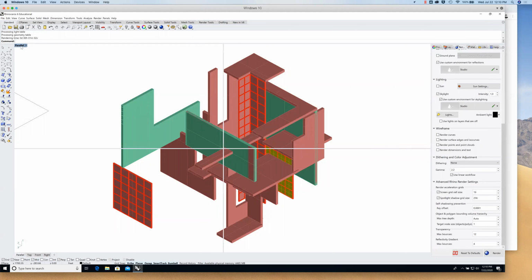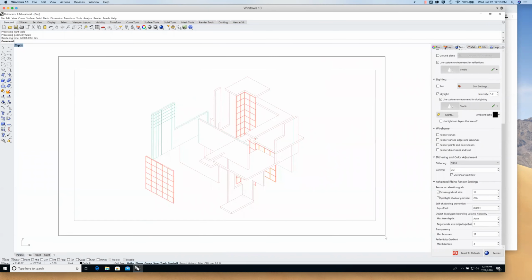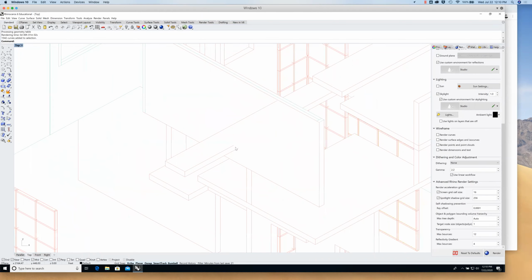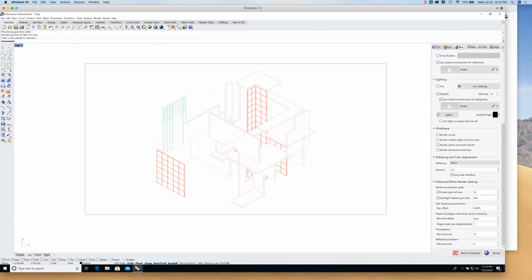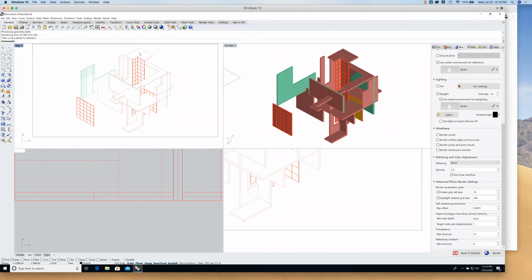So last but not least, I have this drawing and it's in top view. I need to go ahead and export this out as an Illustrator file. A couple of things though. First, what did I forget to do? I forgot to do the intersect command. And so places where things intersect through weren't drawn, of course, right?